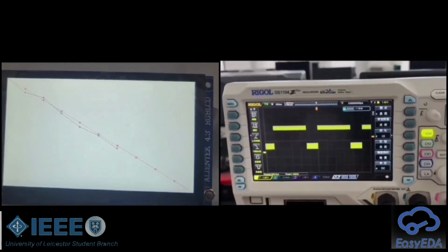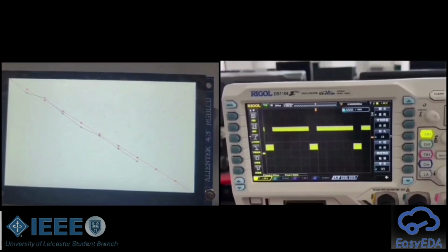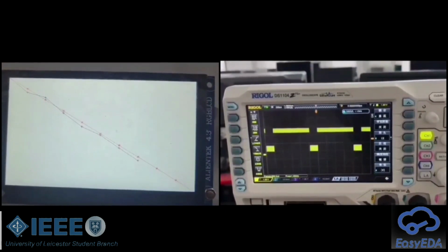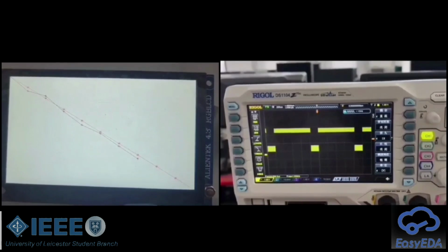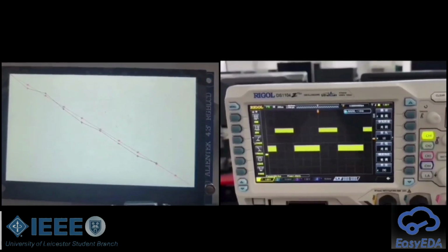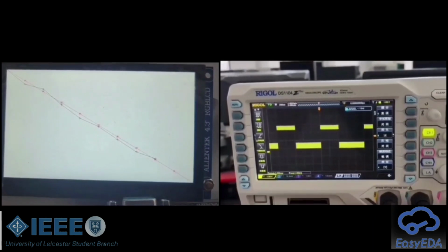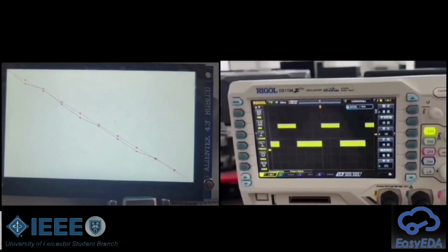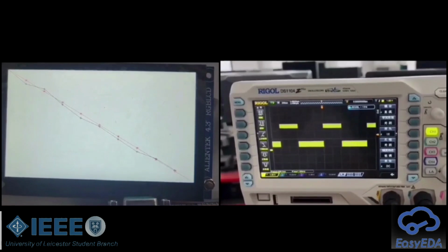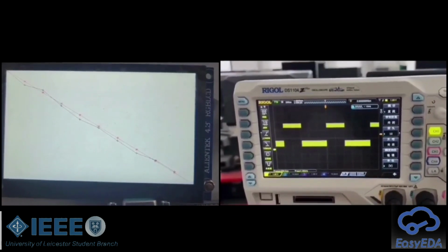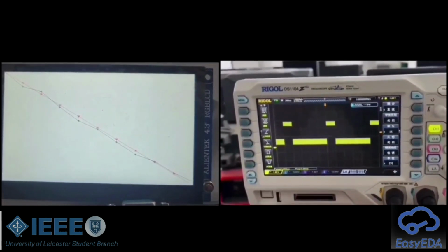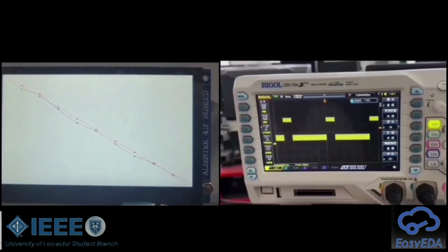The high-frequency signal becomes less. When the PWM signal decreases, the output power for the motor will also decrease, thereby achieving the effect of reducing power consumption of the power supply. This is the method of adjusting the power condition based on the remaining battery charge.